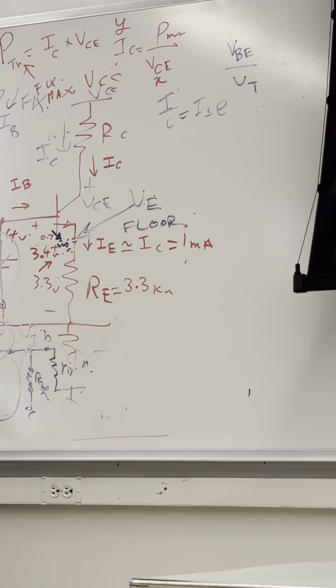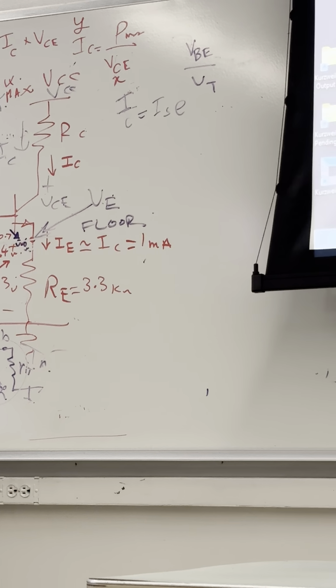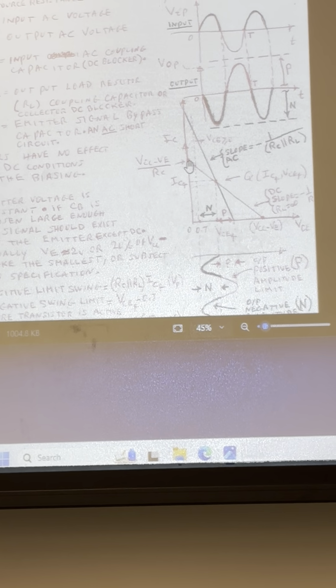This is the foot of the load line, where the transistor will go into cutoff. And this is the top of the load line, where the transistor will go into saturation. That's called the DC load line. The DC load line must be chosen in advance, and it does not determine the actual swing, how much AC voltage and current will move in the plane of the transistor. Remember, this is the transistor plane, the IC-VCE plane. So we're going to move in that plane under the signal.